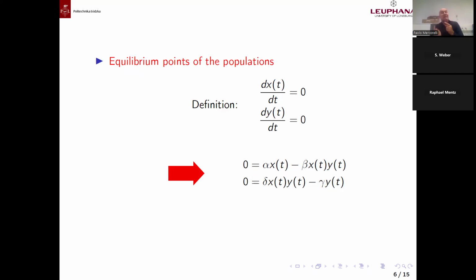This means that we look at the neighborhood, the vicinity of the point, and ask whether it is stable or not stable. This is related to the concept that in nonlinear systems, the stability characteristic is not a global characteristic. We cannot say that a system is stable, full stop. We can say that for linear systems, which could be time variant or time invariant.